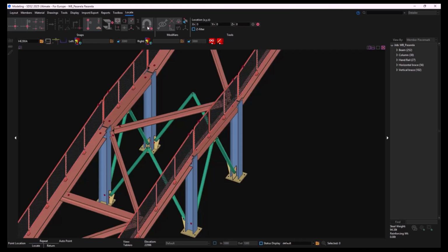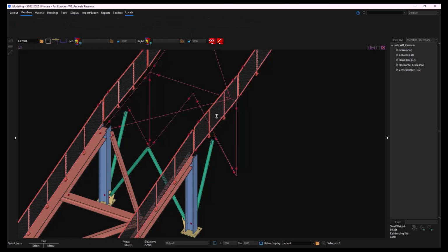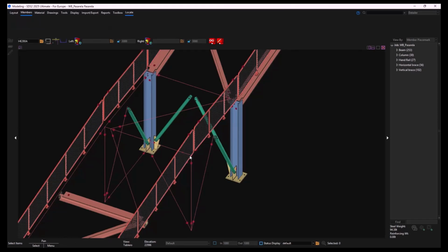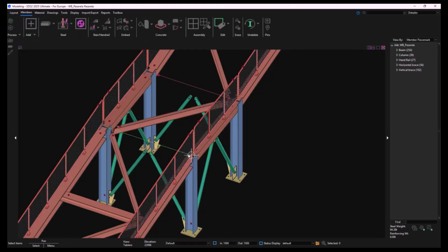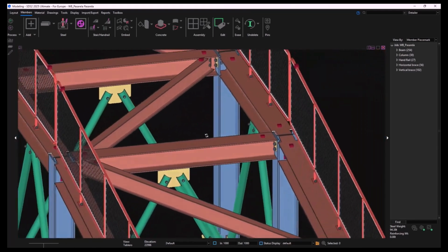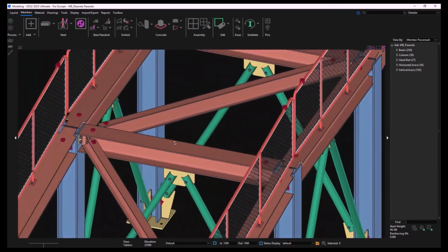Here we have this option, this automatic recognition, where, look, when I approach my mouse to the element, it will recognize automatically where it should put the beam. In that case, just click here or here, and now a combination of the keyboard, just to make it solid and show it.